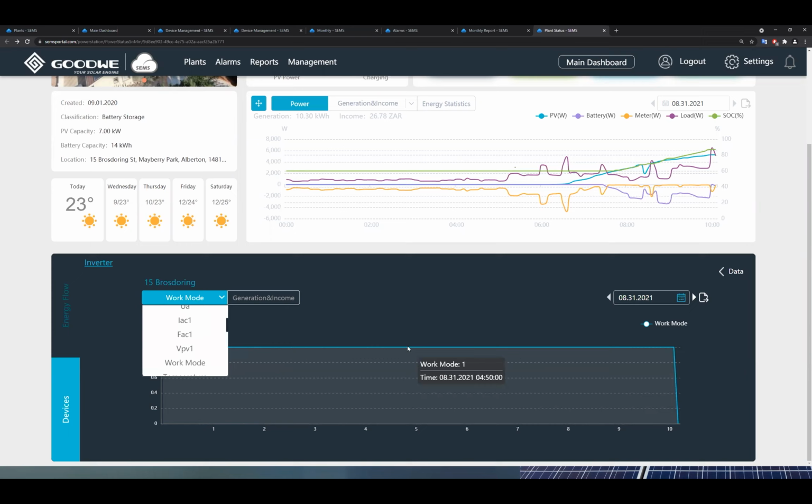But even if there's a grid error, or the grid frequency or grid voltage goes out of range for NRS and we disconnect from the grid, you'll also see this work mode change, like work mode 2, so it's essentially running off grid. So there are a lot of different scenarios that can happen here. It's not necessarily the work mode that you select on the app. It won't change from general to backup mode on its own. It's all based on the current operating logic of the device.